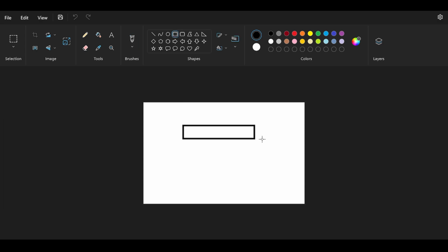You would have a beam like this, and you want to cast the beam. Now, when you cast the beam, you will have to apply, or you have to provide something called formwork. So before you cast the concrete, you provide formwork from the bottom, and of course you provide formwork from both sides. Of course I cannot draw the sides because this is in 3D. I don't want to lose you. So that's my beam now, and I'm only talking about the bottom formwork. Okay? There is of course side formwork, but now I'm talking about the bottom formwork. The bottom formwork that is in red color.